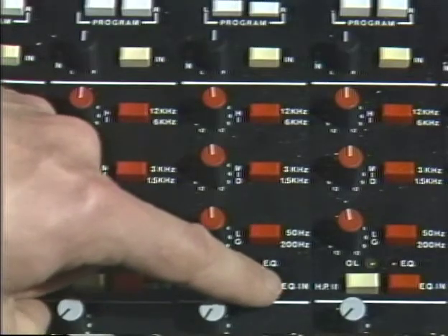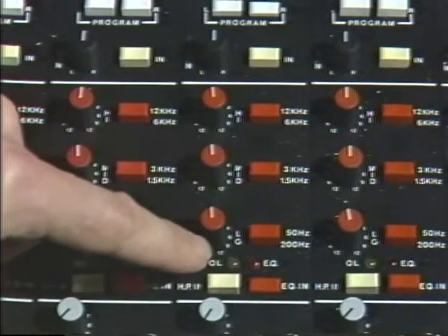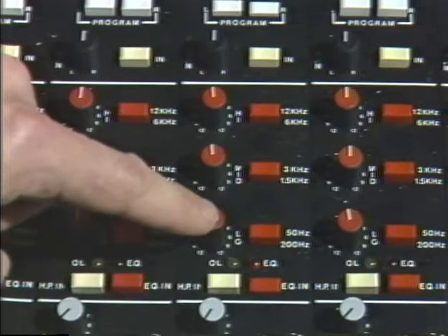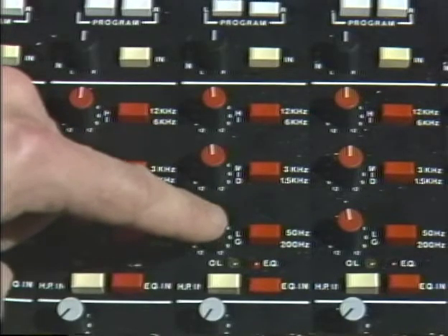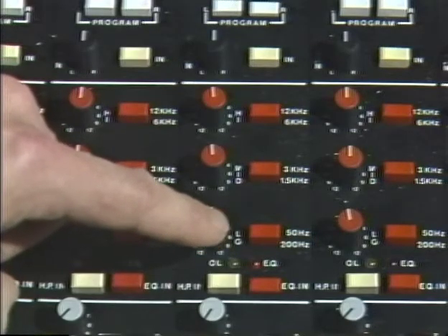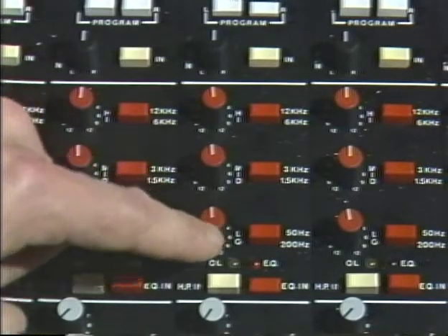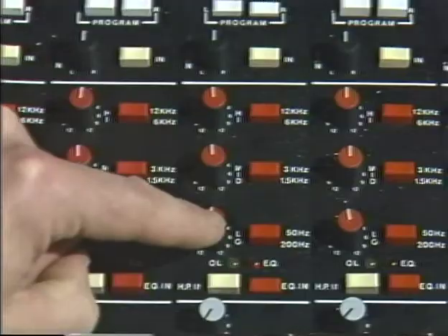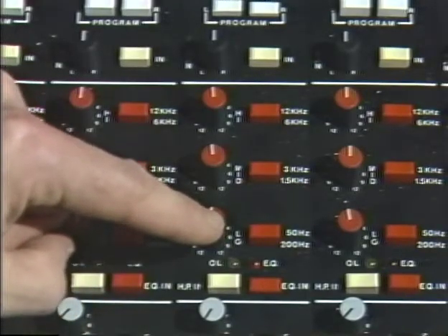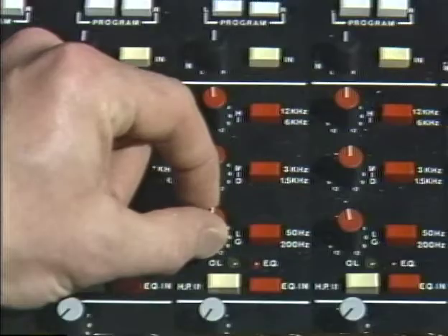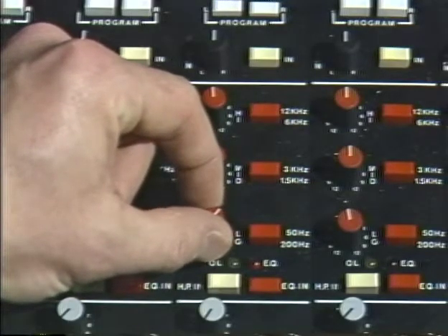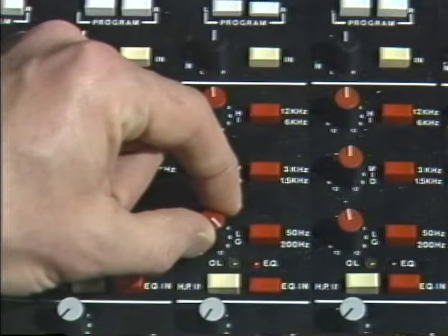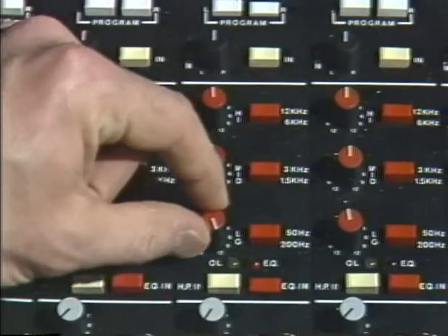Let's, though, now with the equalization in, demonstrate the effect of boosting or attenuating the low and high frequencies. And again, I think to demonstrate this, it illustrates the point the best if we have a little background music. So Maestro, if you can bring that up. And so now what I'm going to do is first boost the low frequencies, and that's what this potentiometer knob will do. So now I'm increasing the low frequency gain, and in fact all the way up to 12 dB when I have the knob over as far as I've gone here.